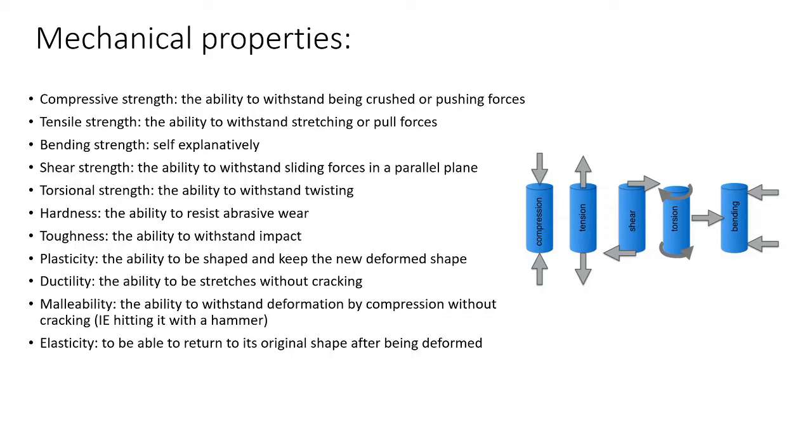Then the next two are the ones that get mixed up a lot as well, ductility and malleability. Ductility is being able to be stretched without cracking, whereas malleability is being able to be deformed by compression without cracking. Malleability is essentially like, if anyone's ever watched anything on the Discovery Channel where they make custom bikes or cars,